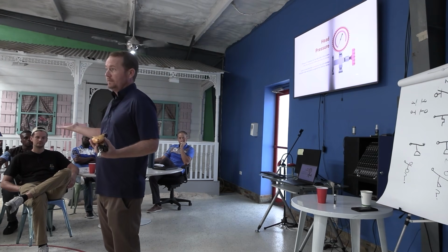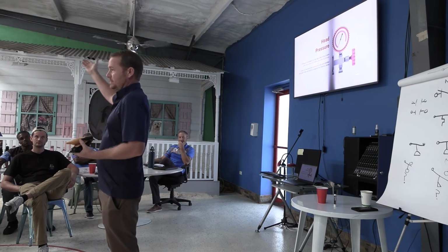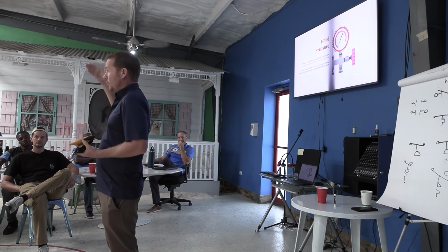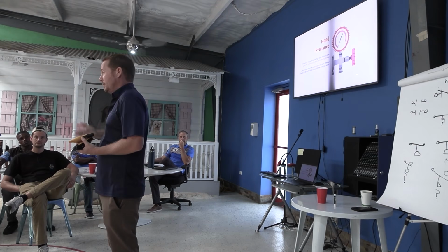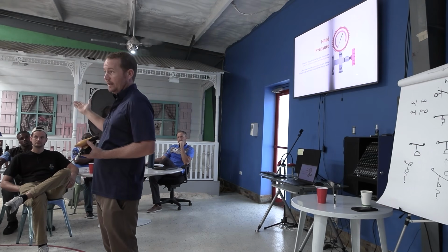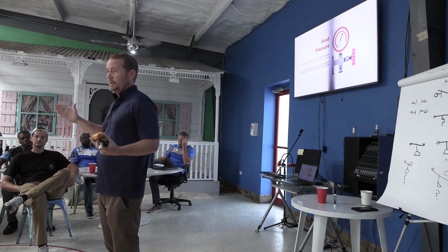And that's really important, because if we feed our metering device with something other than fully liquid, then our metering device cannot do its job. Our evaporator cannot feed properly. It is not designed for that. So we have to have a full column of liquid.